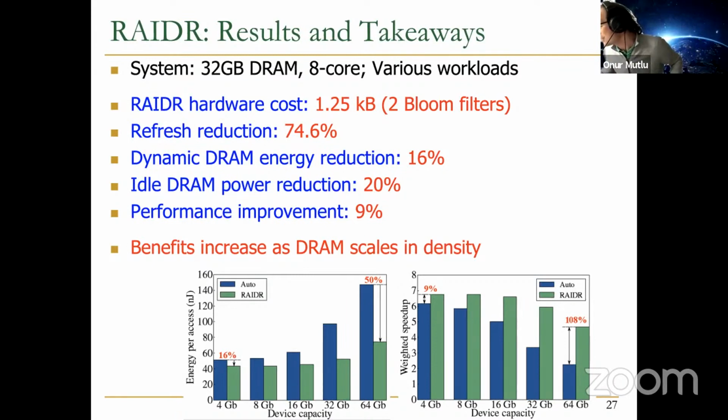Okay, there are 2 questions I will try to handle. I really wonder if this kind of profiling has to be updated frequently. So not all of it, but some of it needs to be updated frequently because of this variable retention time problem, the quantum-like effects that I mentioned, where your retention time changes. So you need to have some dynamic capability to update the profile. So that's a very good question, actually.